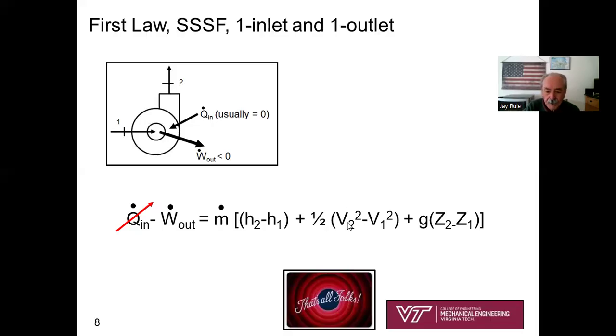Kinetic energy terms, of course, the kinetic energy change depends on the diameters of the inlet and outlet. So do you see, for a pump, if the density is the same at 1 and 2 for incompressible, and the pipe diameter is the same at 1 and 2, then there's no change in kinetic energy. So that's kind of a neat observation of pumping for incompressible liquids. If the pipe diameters in and out are the same, there's no change in kinetic energy.